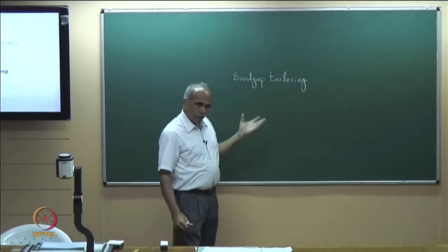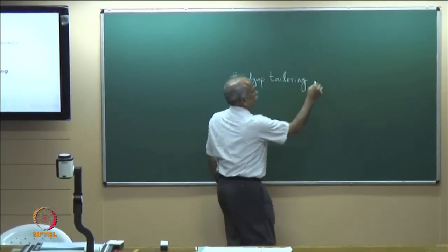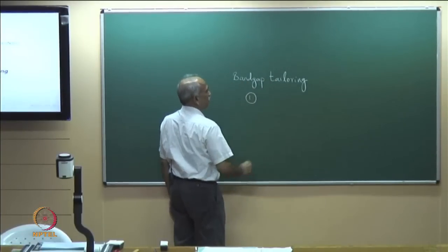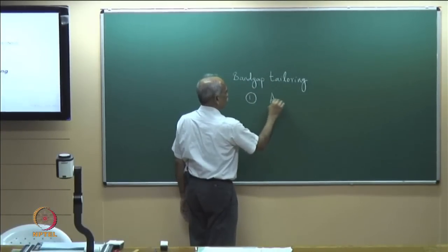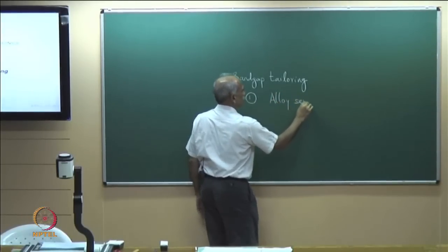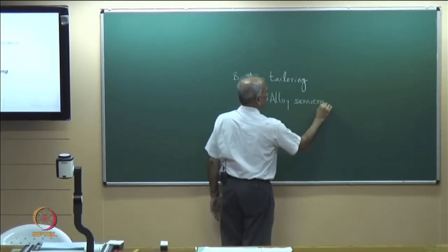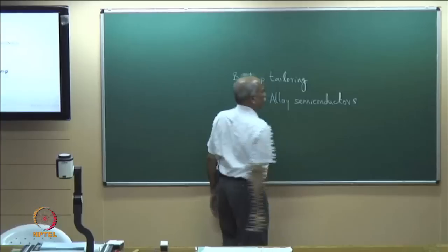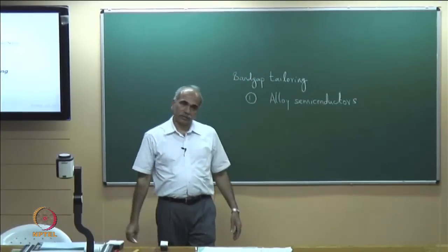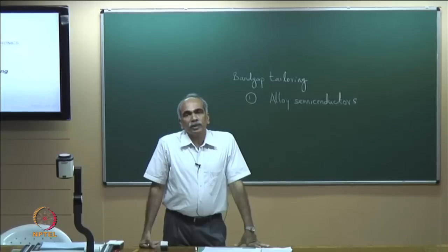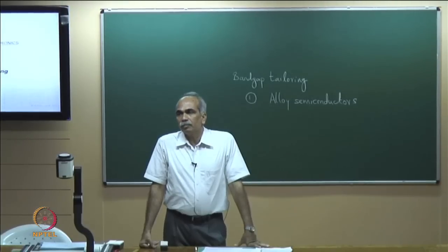We have seen some of them. Some of the techniques which are used are, first, which we have already seen, alloying, or use of alloy semiconductors. By alloying, taking different compositions, you can realize materials which have different band gaps.